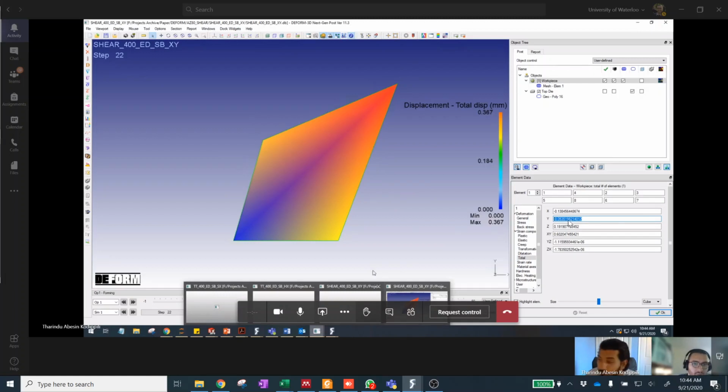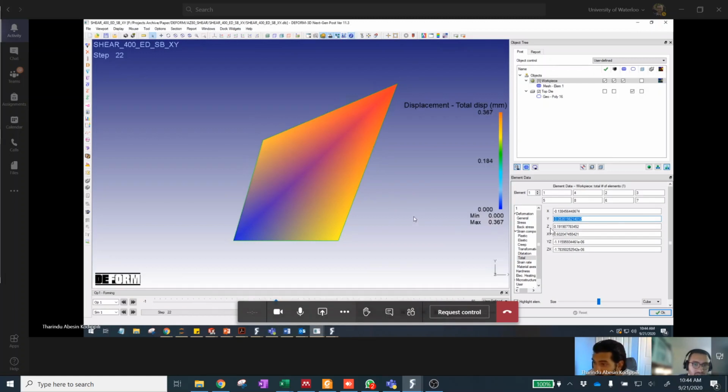Okay, before you jump forward, the X, Y, and Z strains here are negative 13%, negative 5%, and positive 19. Go back to the stress components for the axial stresses: negative 50, negative 40, and then 0.64 megapascals. The positive 5% strain should give more than 0.64 megapascals, which is weird. But anyway, at least it's negative, negative, positive.